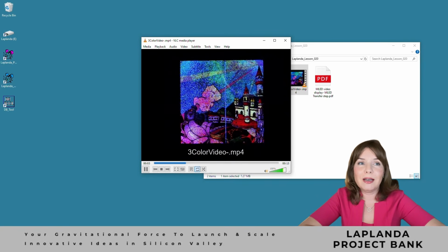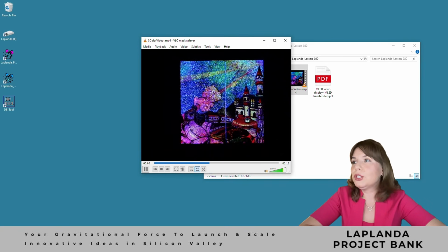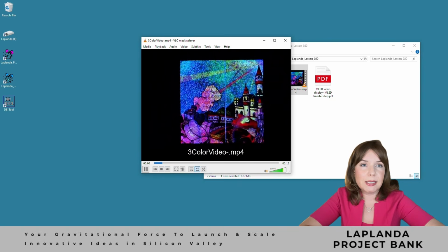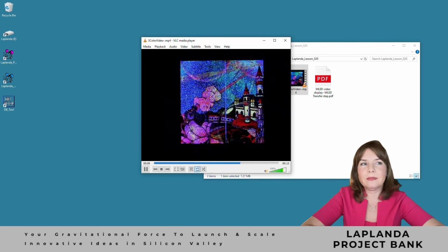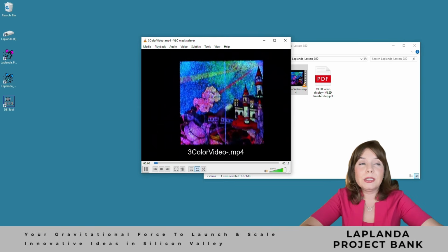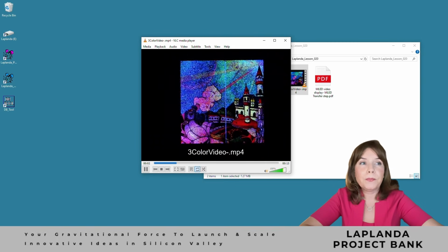The display itself fits on the tip of a finger. What you see here is simply an enlarged version. Let's say I know that on the production line, one of the stations, or rather the process performed at that station, takes the longest time, which slows down the entire manufacturing process. One obvious solution would be to multiply the number of stations, turn one station into 2 or 3, but this would also require 2 or 3 operators, and from an economic standpoint, this is not efficient.